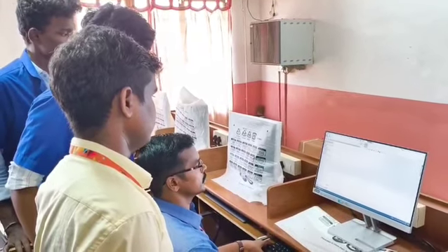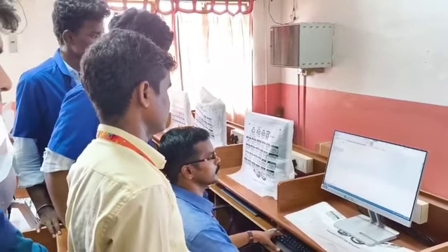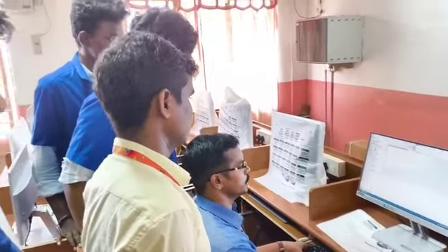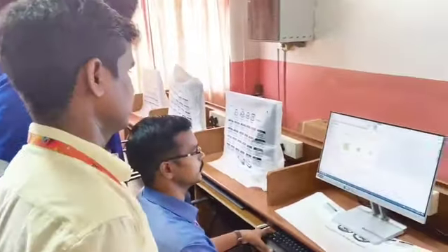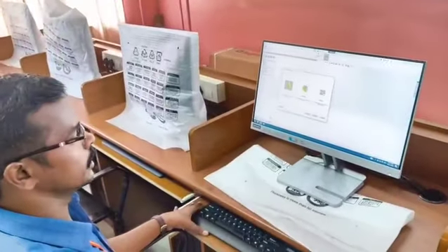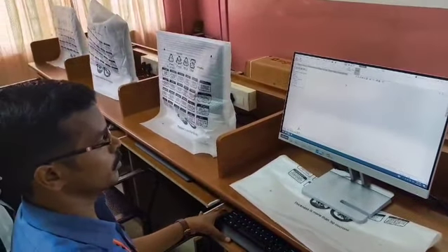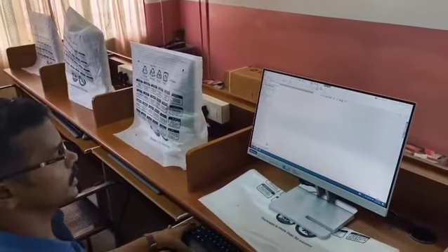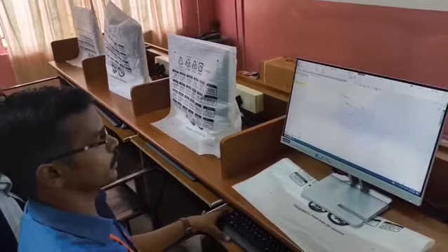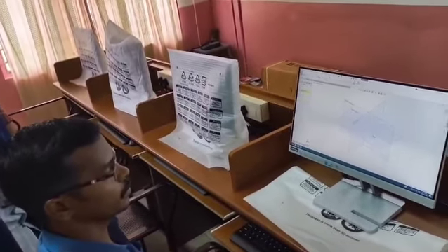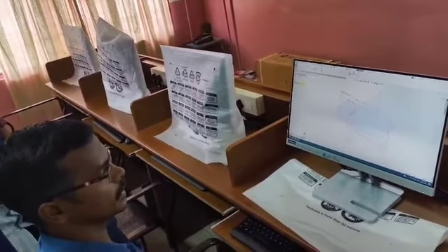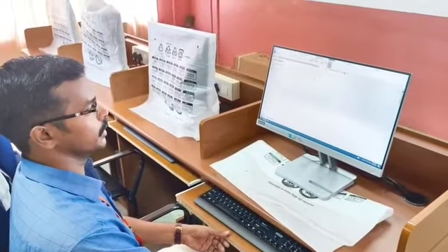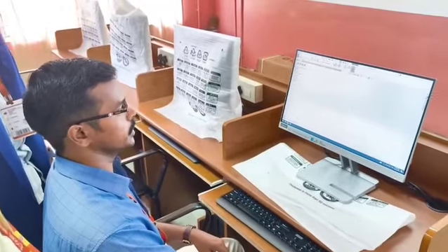Okay. For this I will just create an extruded boss. After opening the SolidWorks environment, you have to go to File and give New file, and in that select part and give OK. After the part environment opens, you go to the sketcher module and click on sketch for creating a sketch. Once you click on sketch, it will ask which plane to select. You can select any plane based on the geometry, and for this feature I just select the front plane. So you have to draw the front view of the object.